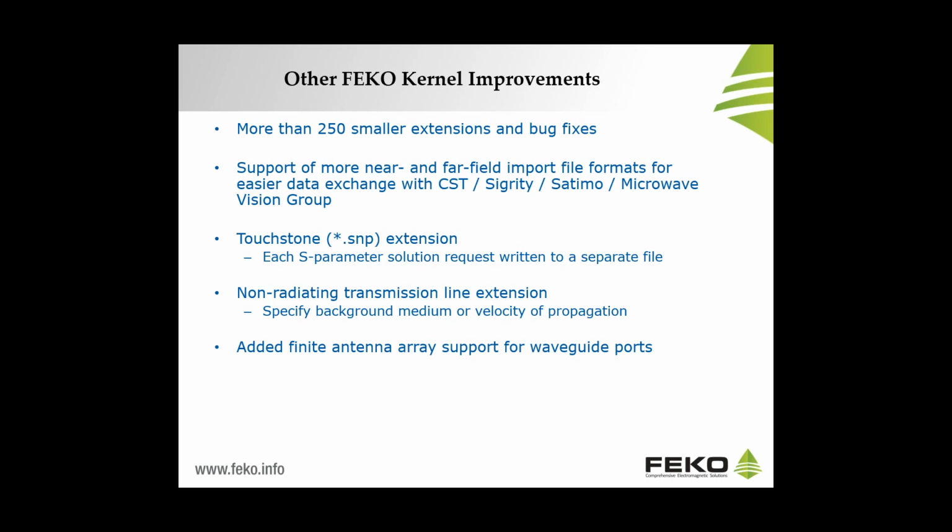And now you will be able to also use waveguide ports when using this feature. And finally, we have increased the accuracy of the Green's functions calculation for distances larger than 10 lambdas.